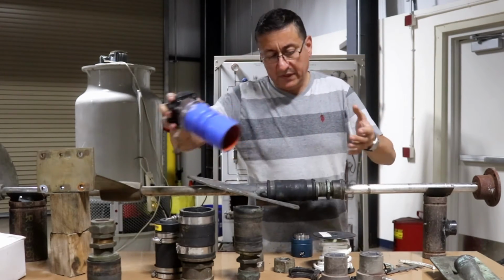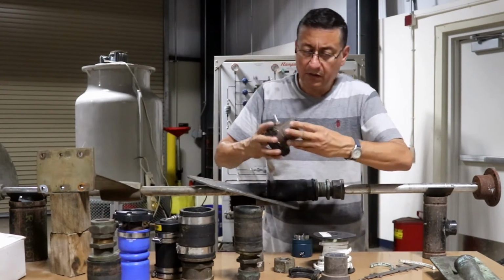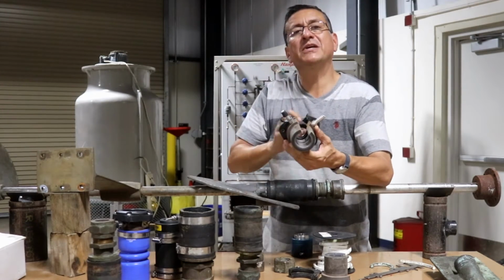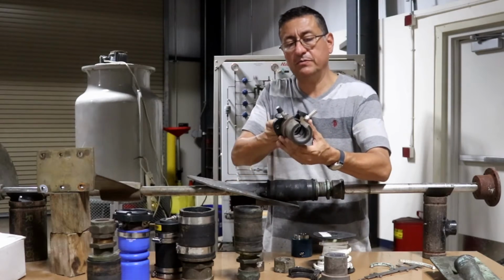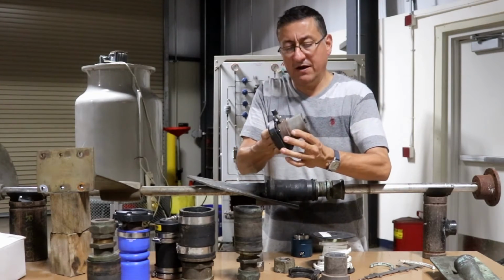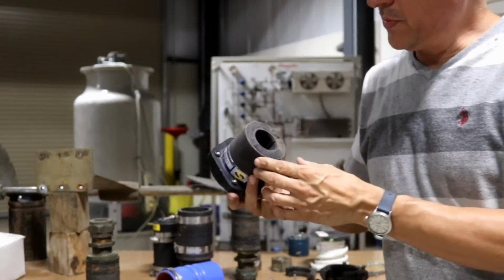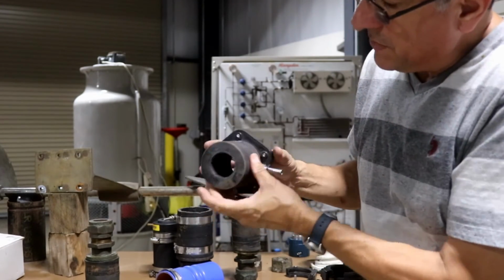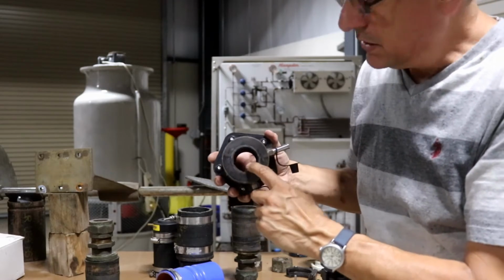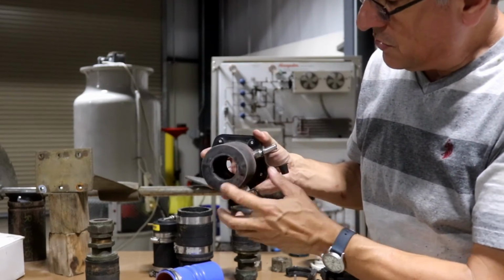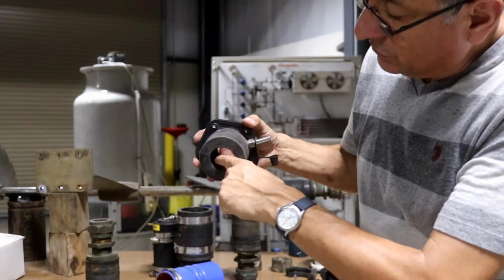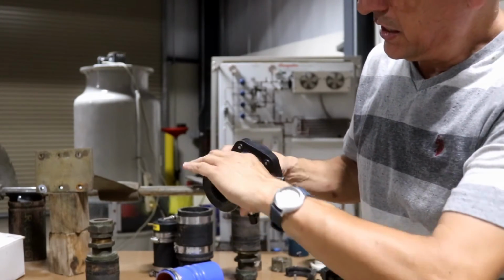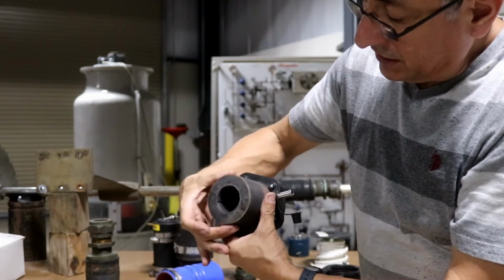In this area, we have a bearing in a special Teflon, a special composite material, and we have lip seals. This is the component. It has a rubber bearing, a special composite material, neoprene, with grooves to prevent the water from passing and keep that bearing lubricated. And this is a special composite material, carbon fiber.